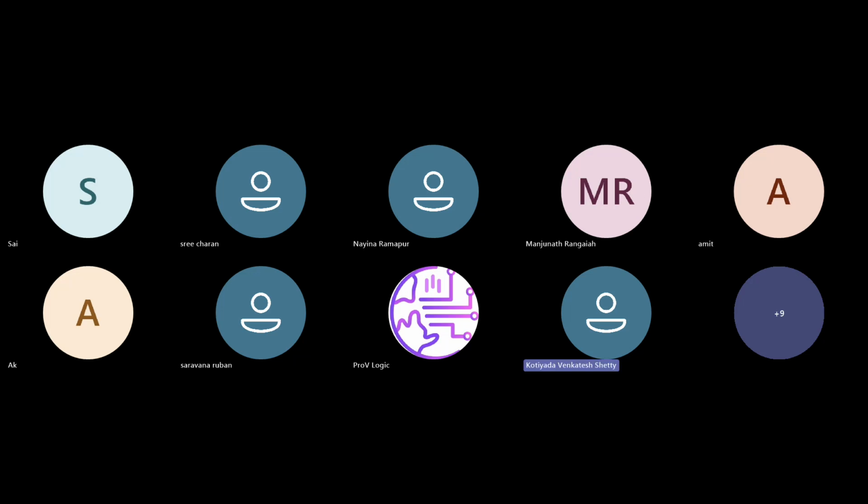In the physical layer we got to know it is physically attached, physically connected, but it needs the configuration of each device, which we get to know by the enumeration concept. Tomorrow we can discuss enumeration. By enumeration, the software will read the config transactions, and we get to know what features the device, endpoint or root complex can support. By that configuration, we get to know how many devices are connected to the fabric.